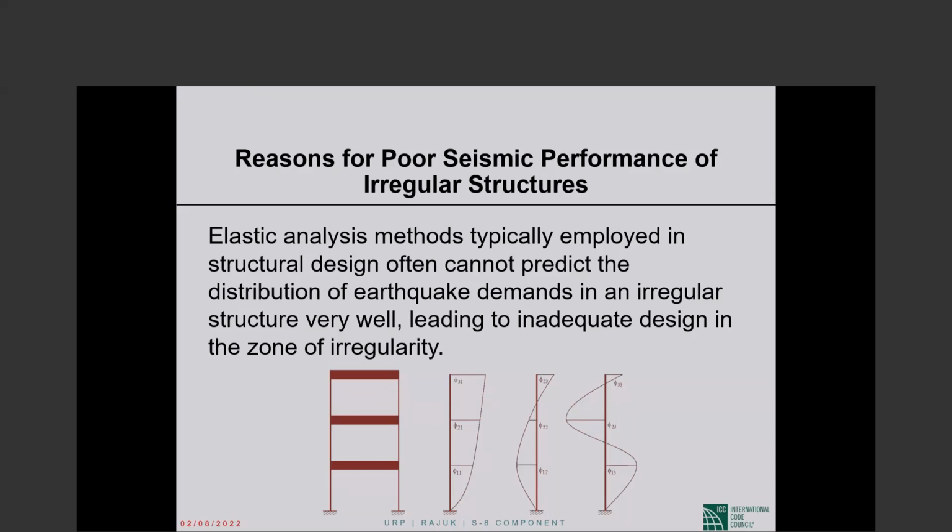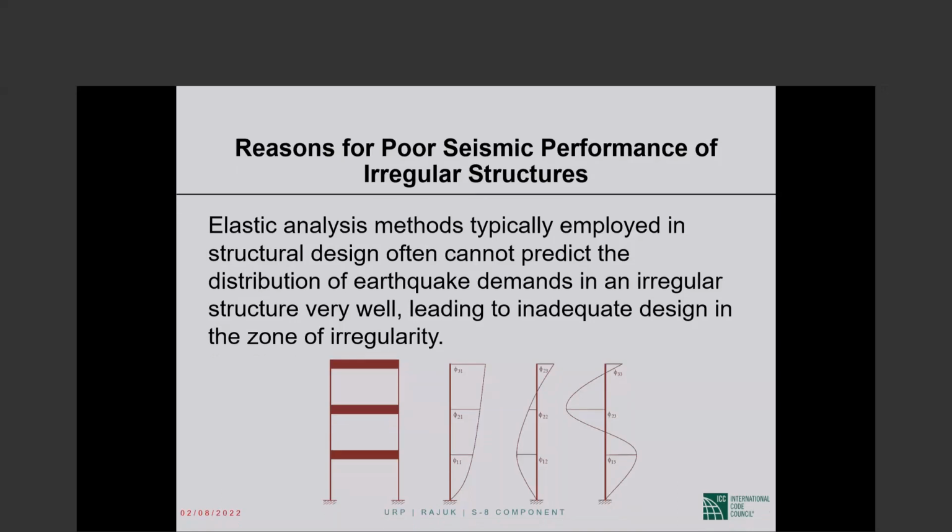The building with the two open faces and two back faces with walls that I mentioned. When the shear wall is damaged, the structural behavior is not regular anymore. So how would you find out from elastic analysis what is happening subsequently to the shear walls and more importantly to the columns? You cannot, there is no way you can figure out the actual force distribution after the behavior of the structure has become inelastic.